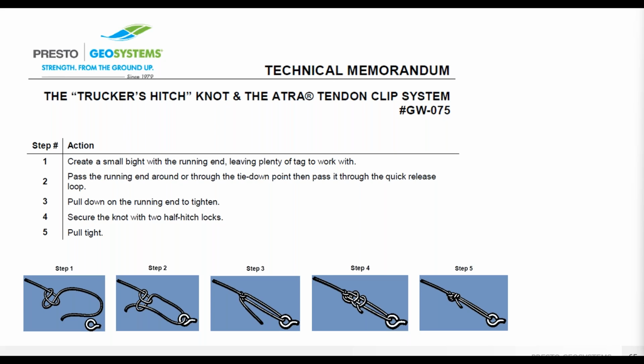There are many ways possible to tie off the tendon to the crest anchorage, whether that anchors a deadman, an earth anchor, or some other type of system. The specific knot type is up to the contractor to determine, as long as the knot is secure and permanent.